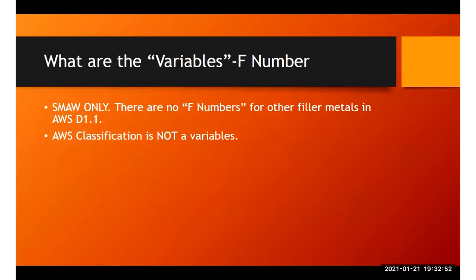And then the way that the wording is in most codes, it says radiography may be substituted for bends, except for GMAW short circuit. Some folks think that radiography is the norm and bends are an option. But really, if you read the way the majority of codes that have welder performance qualification requirements do, bends are the norm and radiography is an option. And of course, the exception is the short circuit mode, like you said. So that's a good point.